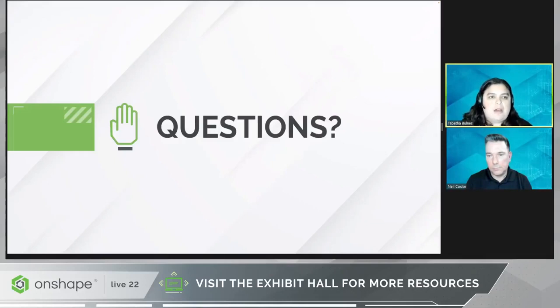But what's great about Onshape is they're always improving. One thing they've improved on is they've released this feature script called Query Explorer, and it is saved on my toolbar. If you're interested in learning FeatureScript, it should be saved on yours as well, because it saves so much time to quickly go through the Query Explorer and see why I am not picking up what I thought I was.